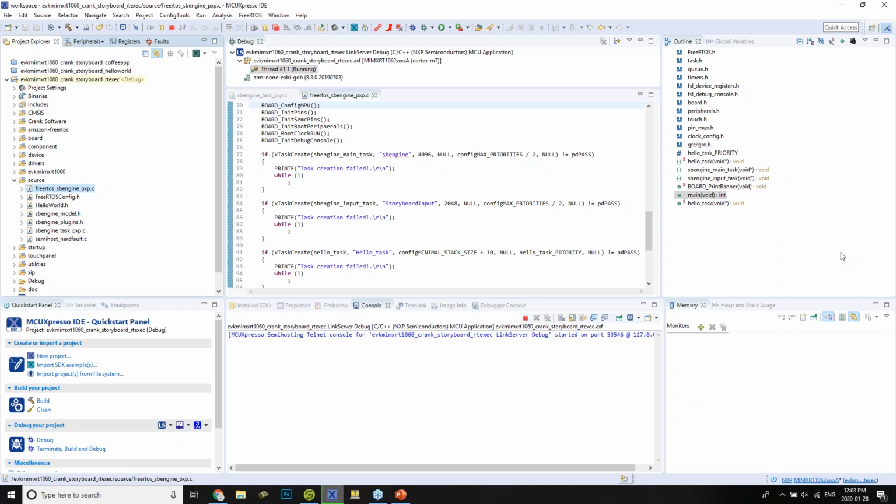The main thing is having enough hardware for what you want to accomplish. If you have enough memory for your display frame buffers, which is simply width times height times color depth, and generally a couple hundred K of RAM, conservatively, since we don't know the goal of your application, then we can conceivably run there.